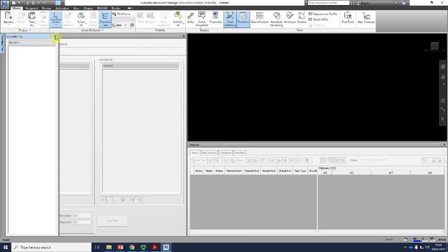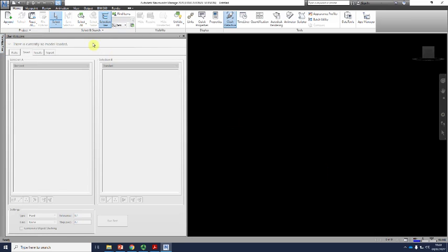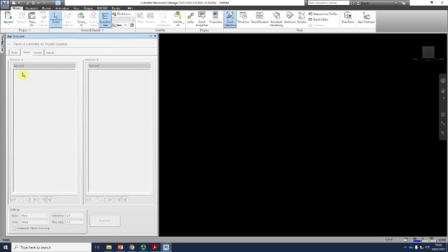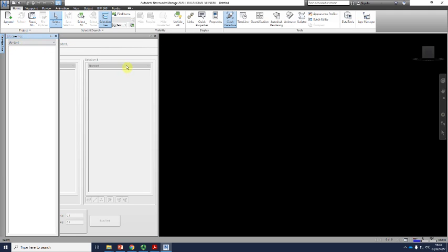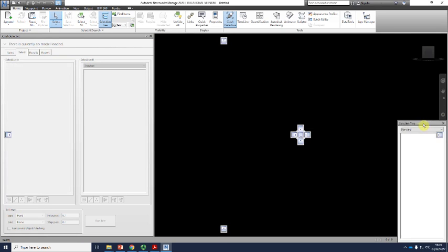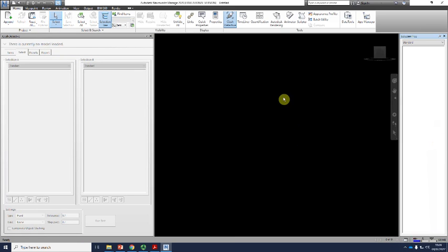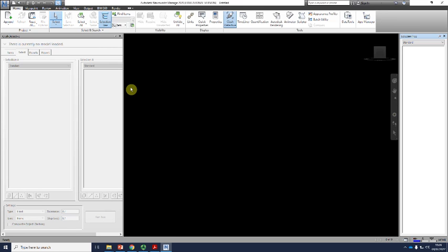The other thing is, let's say you're doing a clash detection. I have my window pinned here, and my selection tree is here. I can probably place it somewhere here, on the side, depending on work preference. If I want this window layout to open regularly because I'm working on clash detection, you can save the view without having to pin the windows again.